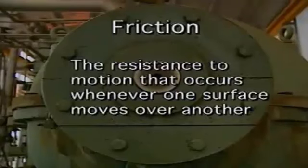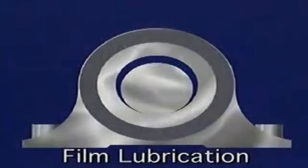A major function of bearings is to reduce friction. Friction is the resistance to motion that occurs whenever one surface moves over another. In sliding surface bearings, friction is reduced by a process called film lubrication. Film lubrication is a process in which a film of lubricant is distributed and maintained between the bearing and the shaft as the shaft rotates.